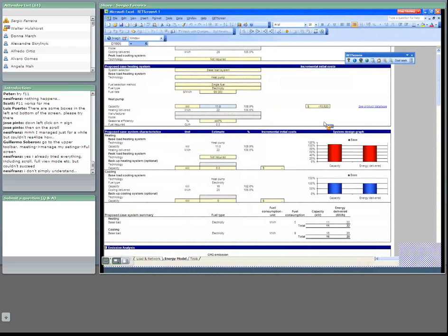Yes, I gave the hint in my introduction that indeed a heat pump is very case specific. So whether you have an air, water, or ground or rock based heat exchanger, you will have different circumstances, and that needs to be balanced with your heat load. So you actually need a good previous study to know what your heat load is, so you can properly dimension your heat pump.